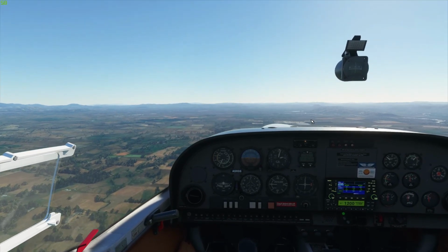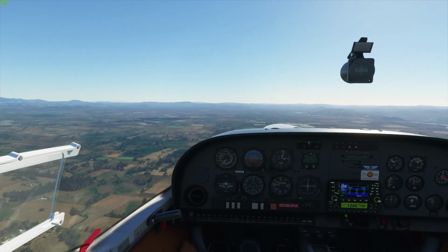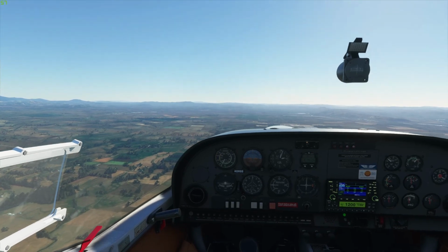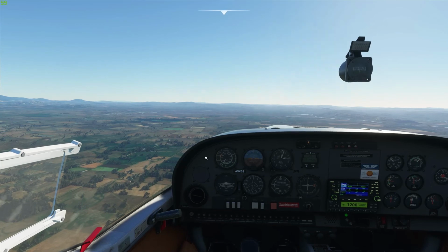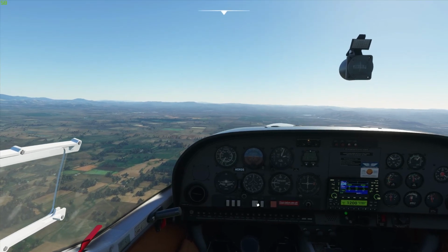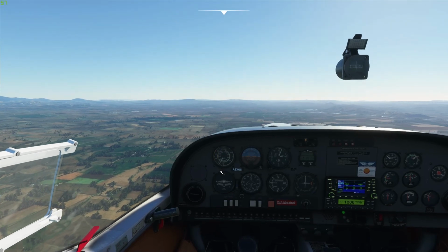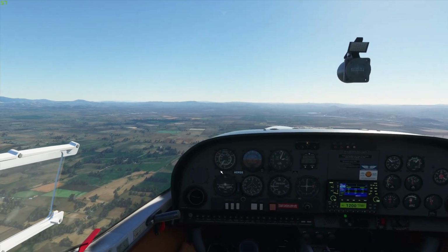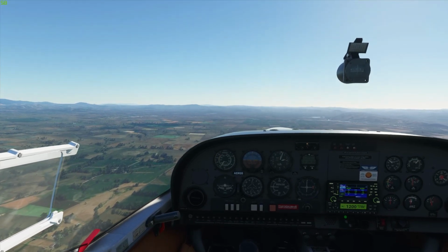Then we will let the aeroplane just do its thing. But it's most important for this that we start in balance, so trimmed out. And we're pretty close there. So 23, 23, still climbing. We've got about 96 knots, and it's really important to be trimmed, so we'll call that trimmed there.